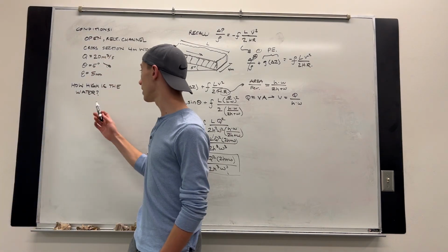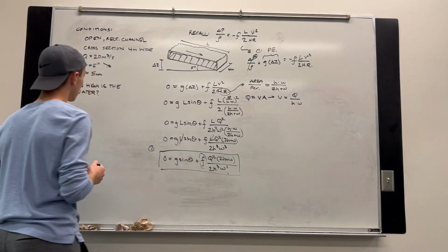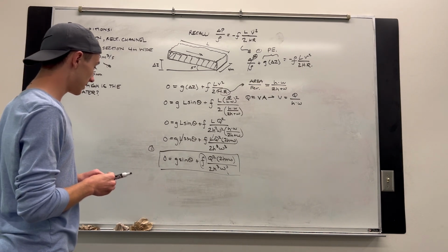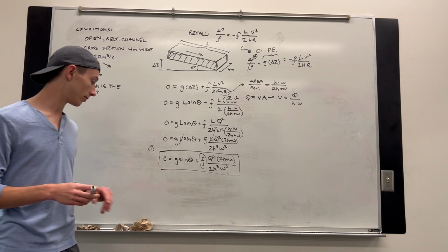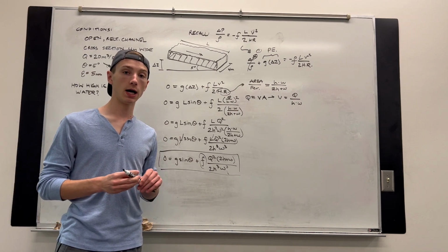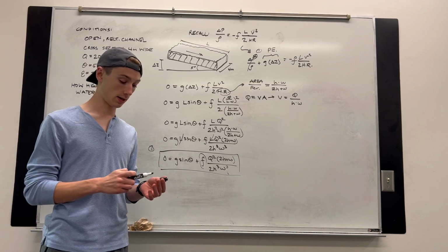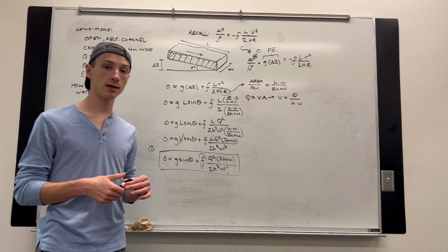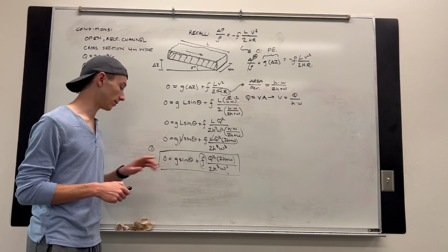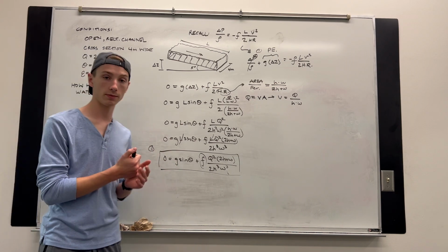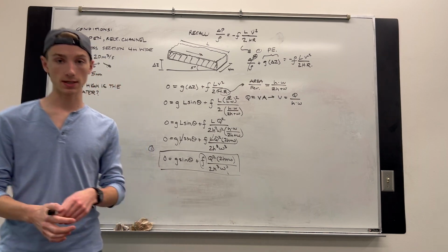We know the roughness, but we don't necessarily know everything about the Reynolds number. So our second equation is going to be a modified version of the Colebrook-White equation, which I will join you on the computer for in just a second. We're going to use both of these equations, set them both equal to 0 and then optimize them. All right, so join me here on the computer and we'll keep this going.